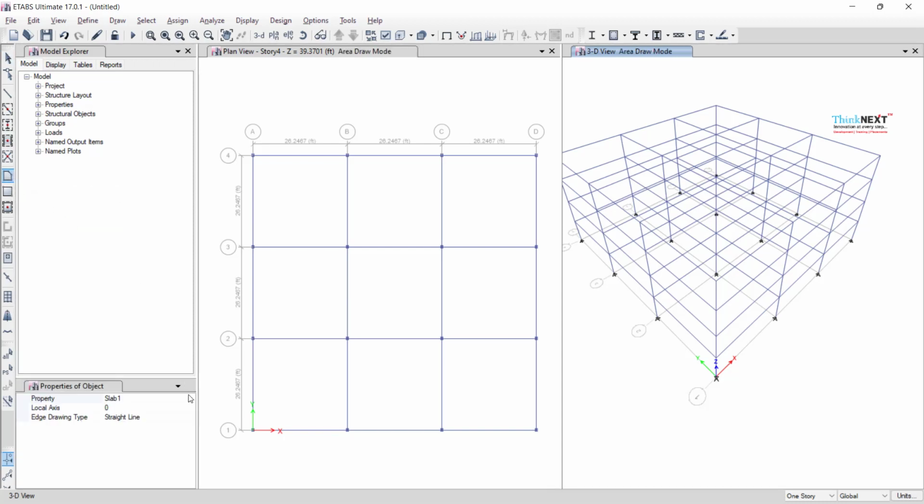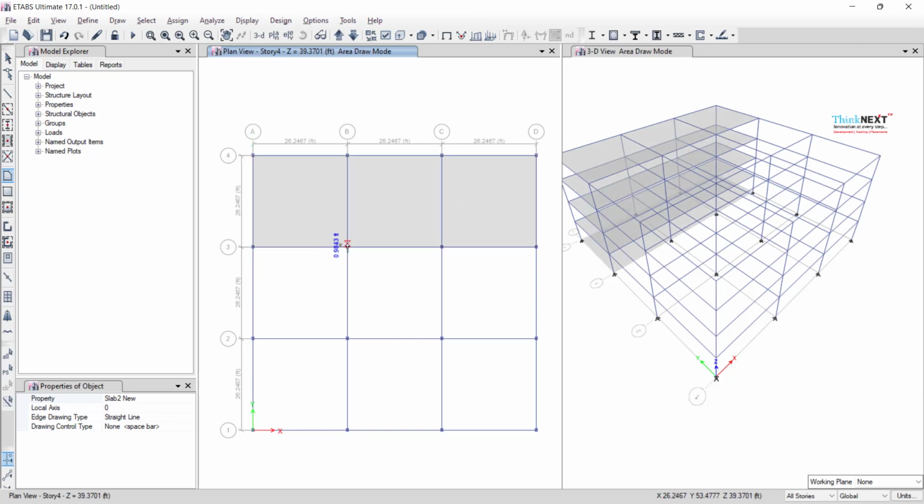We just have to click here and select our slab new option there, and remain one thing, go for this for all stories. Now I have created a slab by using the rectangular portion. Firstly I have started from this portion. Now for this, here and here, when I click here, you can see I've created a slab. So now I have created slabs in 3 portions.